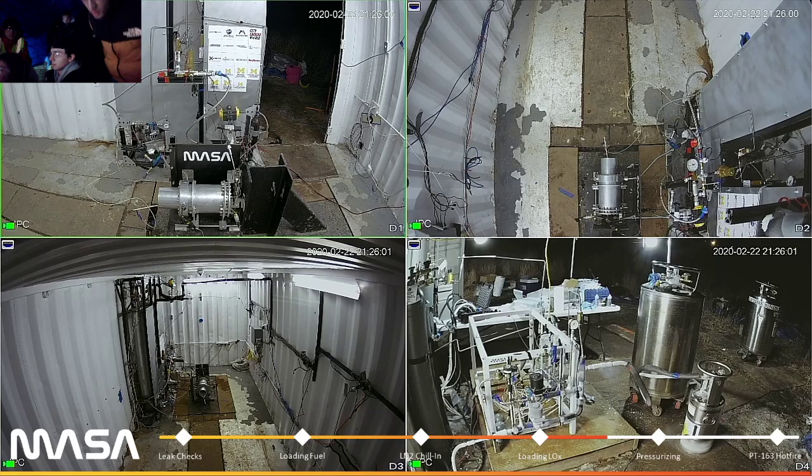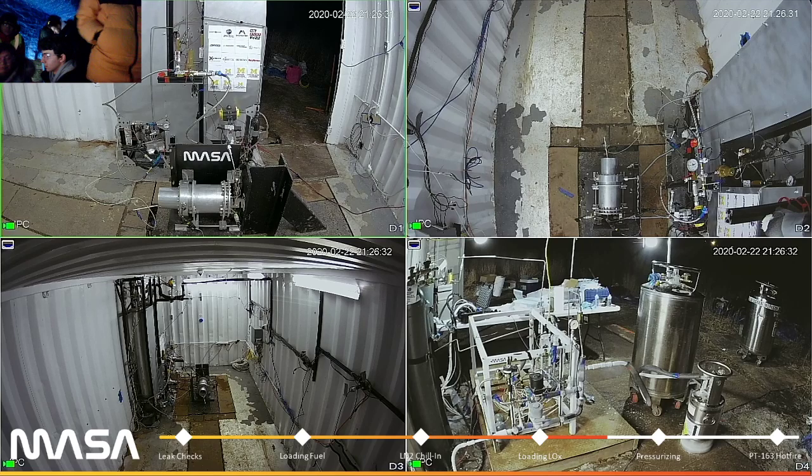Andrew, do you want to update people with something? We have a certain OF ratio on the engine, and we basically keep that OF ratio from ignition to full burn. We don't really have a varying OF ratio. This nozzle is not actively cooled, nor the one that's going to be flying. Our flight nozzle is going to be more of a titanium radiative cooled nozzle.